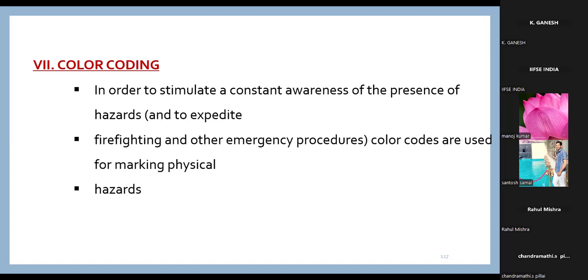Change the ladder. Okay. If the management says that it doesn't have new ladder stock, then what action should he take? Not allow the work. Stop the job. Alternate arrangement for the ladder has to be arranged, sir. There is no escape from that. To arrange for staging, if possible.